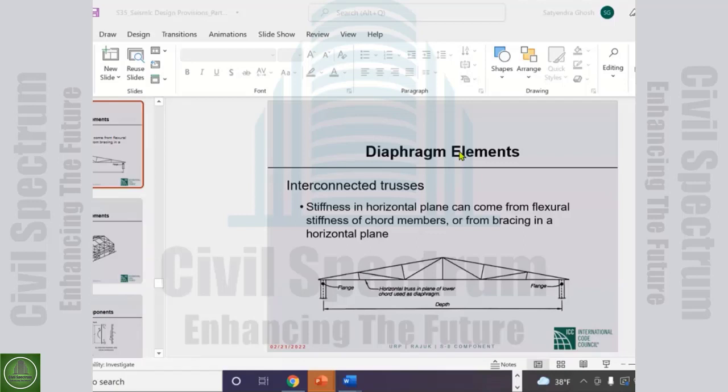Even if you provide shear reinforcement, you will still need a thick mat, a thick podium slab. Five feet may be an exaggeration that you find very seldom, but 2 feet, 24 inches, 30 inches podium slabs are not at all uncommon, and we need that even when we have reinforcement carrying part of the shear.